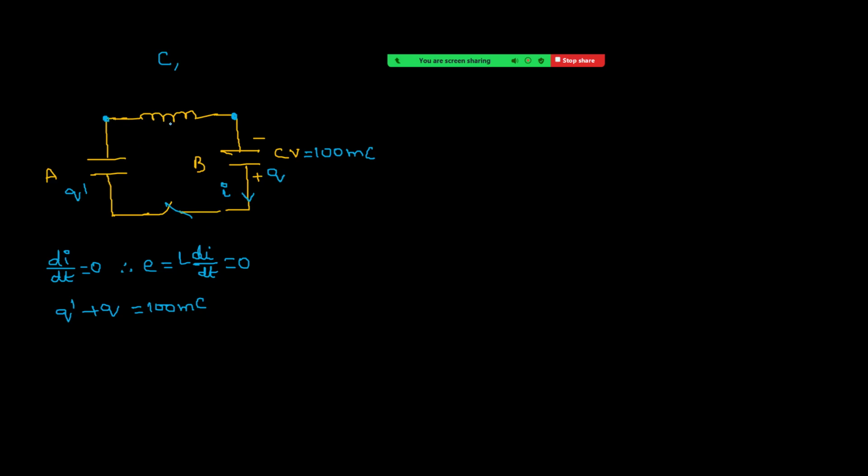If I'm taking from here, first we have to replace the inductor with an equivalent battery. Now you can see initially no current. Now current starts increasing from zero, reaches a maximum value. Then current starts to decrease. So since the current is now increasing, it tries to oppose the cause. So it tries to decrease the current. Therefore, I am replacing this with a battery, and that battery must be like this. Because it has to oppose, it tries to decrease.